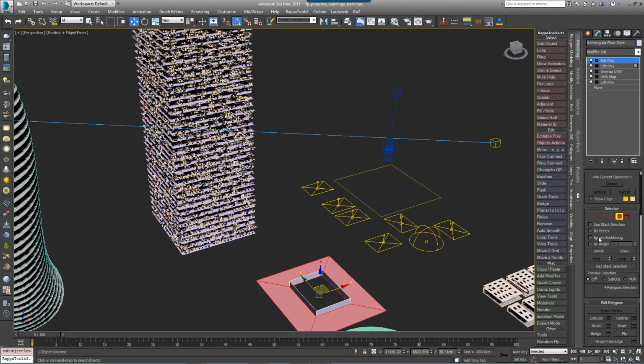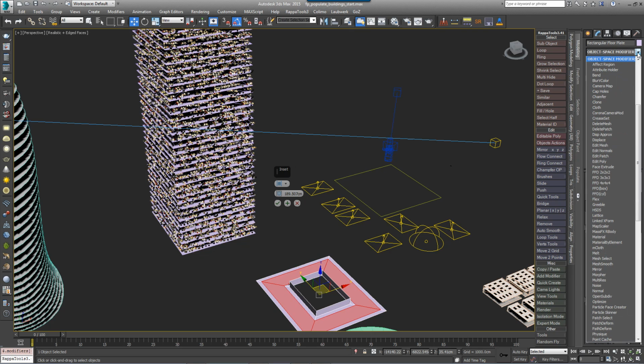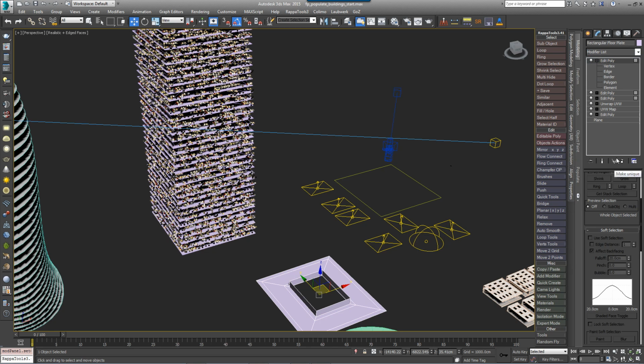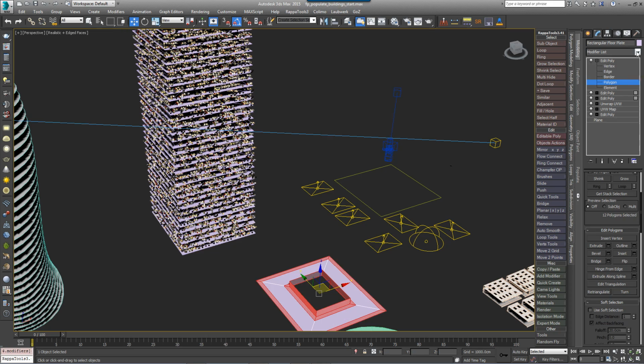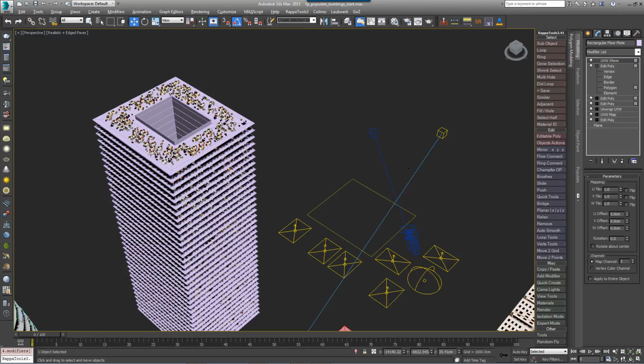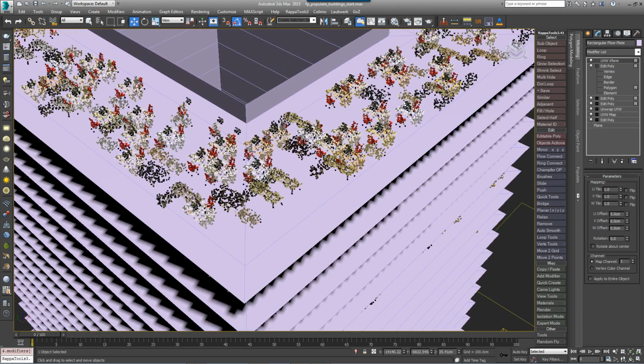The only real difference is that now we only need to edit a single floor, because RailClone will duplicate the geometry for every level. This also explains why we make the white area of the distribution map extend well beyond the 0 to 1 UV space. If we didn't, the UVW Xform randomization effect could cause unwanted black areas to appear in the distribution map. If we look closely at the alignment of the desks in relation to the building perimeter, you can see that they're all facing the same way, irrespective of which side of the building they're on.